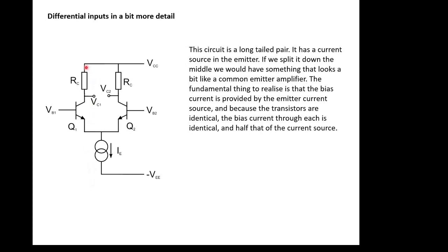So we have to have a certain amount of current flowing through these transistors for them to actually act as amplifiers. Now, in previous work that you probably looked at, you will have put a bias current into the base, which is then amplified, giving us an emitter current, which allows this thing to operate. We can't do that with an input that we wish to connect to DC, because there's no way of distinguishing our bias current from the input signal. So we have to bias in a different way, and the biasing is done by a current source in the tail, which is a fixed current.